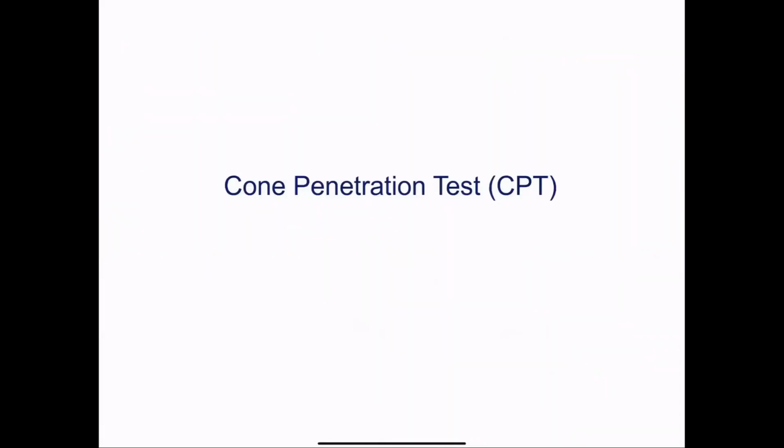Now, the next part of in situ evaluation of ground improvement is cone penetration testing. Cone penetration testing is mainly for soft soils, such as clays. And we use this approach quite commonly for land reclamation projects to see, for example, if we do field surcharge preloading or vacuum preloading, what's the improvement before and after. CPT, if you remember from last lecture, is a static penetration. Well, nothing's really static, quasi-static penetration. We're looking at millimeters per minute. We're not talking about smashing a split spoon or split barrel into the ground.